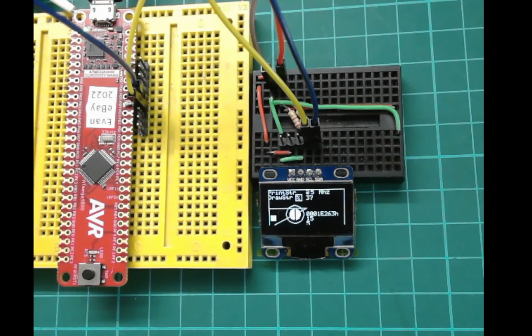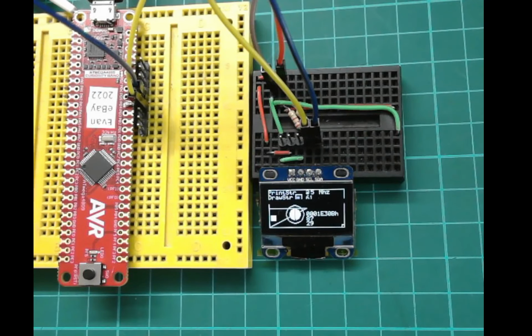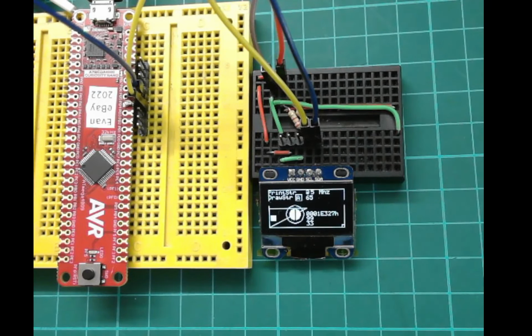Now, to be quite frank, these AVRs are not fast. Even at 20 megahertz, they're not quick. If you take an LGT from China, a clone of an AVR, it is rapid compared to this, but it does it. Now, this may be faster when we use hardware I2C or TWI. It may be, I don't know. We'll have to wait and see. But I'm just going to revert my program back to 20 megahertz and we'll just reprogram it whilst it's doing it.